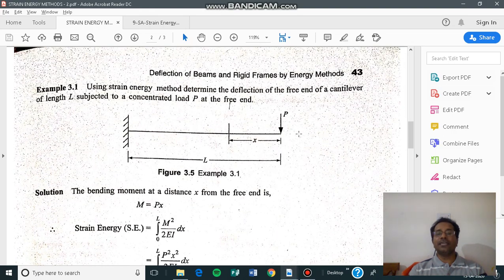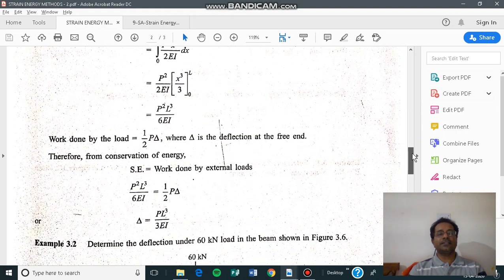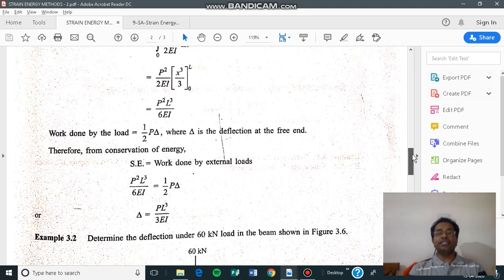Because for the load applied here, the energy stored because of the internal process is not stored suddenly. It starts from displacement 0 and reaches its maximum. It takes time. That's why it takes the average of that, and that's why we get this from the load deformation curve. Also keep in mind, we are applying the strain energy concept for linear elastic structures, where the theorem of superposition is allowed. For those problems this concept is applicable.